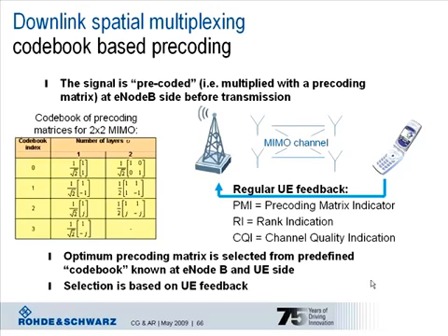And how is that done? The UE is evaluating which precoding matrix would maximize the reception quality. Besides the PMI, the UE also reports CQI feedback, channel quality indication, and also a rank indication, RI, which provides information on the rank of the channel matrix. That information will provide the base station with input on whether spatial multiplexing or transmit diversity should be used. So this is downlink spatial multiplexing based on the codebook based precoding as the other possible MIMO mode, and the base station now has the different configuration options available here.